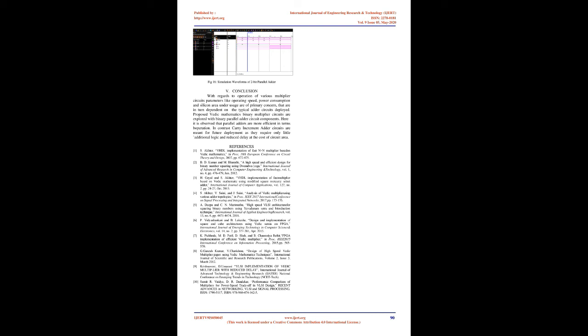D. Half-adder. A half-adder is constructed using an XOR gate and an AND gate. It is meant for adding 2 bits and generates a sum bit, S, and a carry bit, C, as the outputs. Though the half-adder is a simple circuit, it has a major disadvantage of adding only 2 input bits, A and B, and has nothing to do with the carry, if there is any in the input. That means the binary addition process is not complete and hence it is called a half-adder. The logic diagram of a half-adder circuit is shown in Figure 12 below.